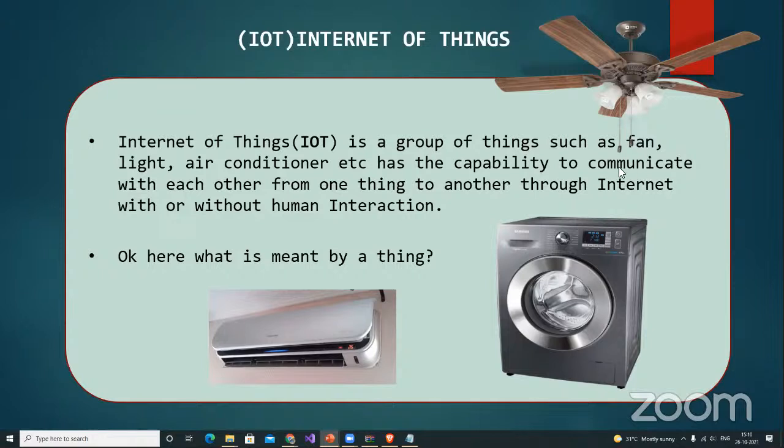Even if you take a fan nowadays, it also becomes an embedded system, not like the single phase induction motor in the previous days. Right now it comes up with one technology called, I forgot it, but the technology is really good. Okay, BLDC, yes, BLDC, brushless DC motor. A microcontroller unit needs to be there to control that particular motor, hence it becomes an embedded system from a general purpose single phase induction motor.